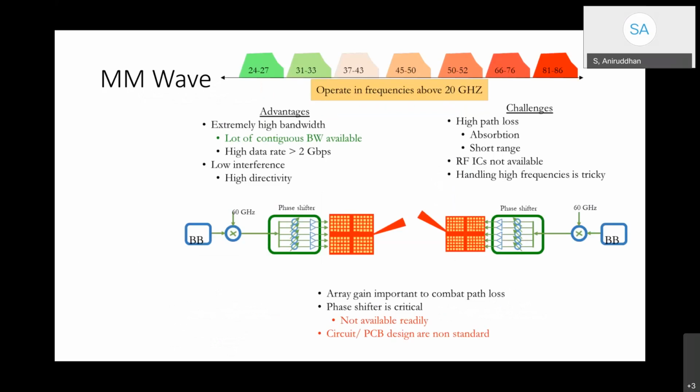So the last aspect of 5G that I want to point out is operation in the millimeter wave band. Unlike the massive MIMO in the sub 6 gigahertz bands, in the case of millimeter wave, there is most probably going to be only one or maybe not too many radios.